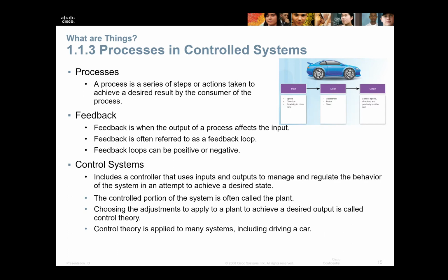It had just one shunt resistor to measure the peak current, and then a low pass filter, RCL low pass filter, to get the filtered data to the Arduino. So there is feedback, and the control system is the one controlling the whole thing.